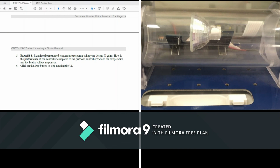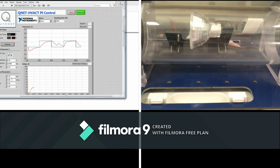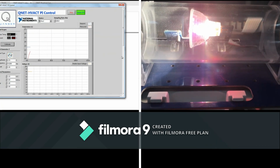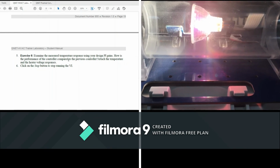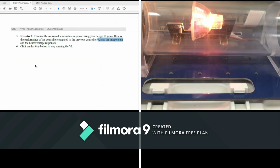And for exercise number 8, we will plug those values into the screen. Imagine that we have our KP as 2.35 and our KI equal to 8.2, for example, and then we run the system only to validate those values and see the effect of our calculation, whether it is matching or not. How is the performance of the controller compared to the previous controller, the calculated one? Attach the response.